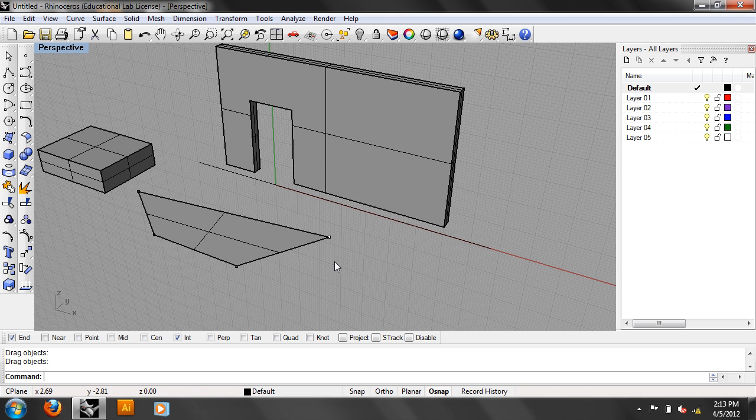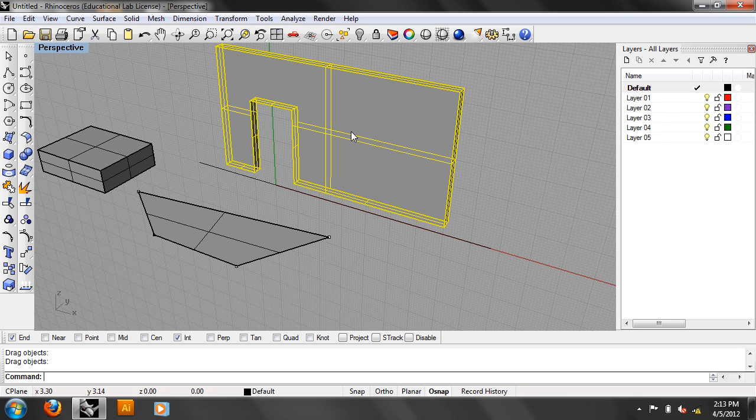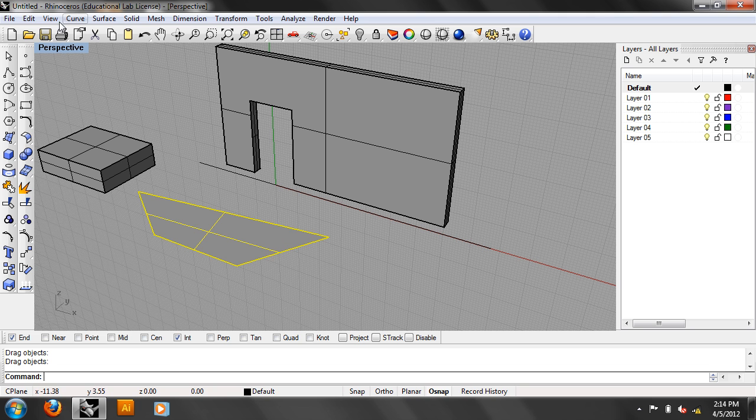Okay, so with what I've shown you, what might be the technique for stretching that wall? If I can't stretch a poly surface, but I can stretch a surface. You're going to delete the face and stretch both sides. What's that? You're going to explode it. Yeah, if I explode it, it gives me surfaces. And then I can pull the surfaces. Okay, yes, very good.